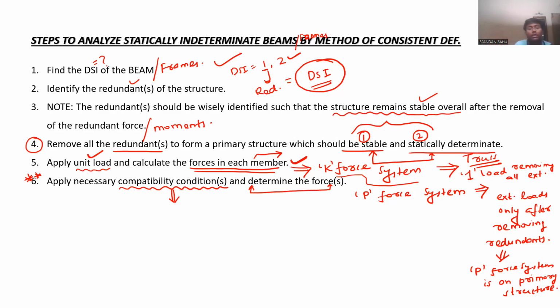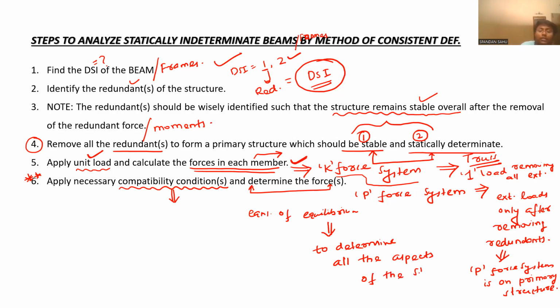Now you can use the equations of equilibrium to determine member forces and support reactions, to determine all the aspects of the structure or truss, let it be bending moment at any point, member forces, reactions, shear force, axial force, anything.